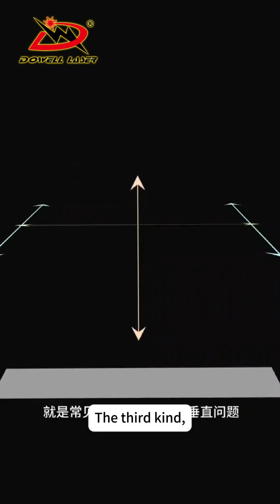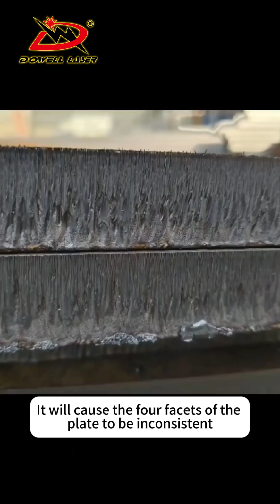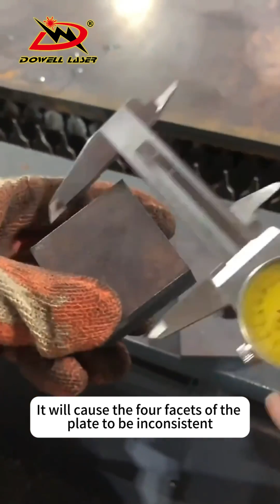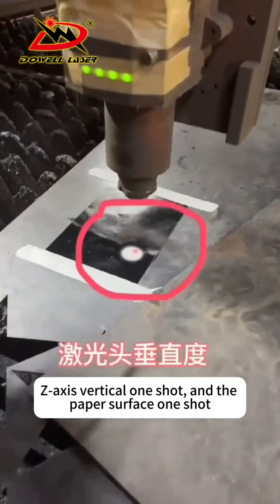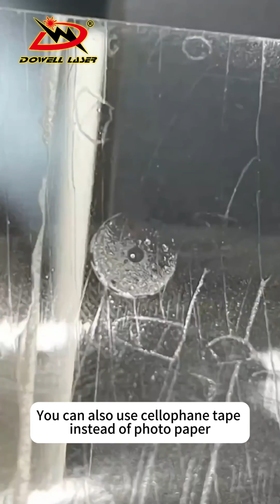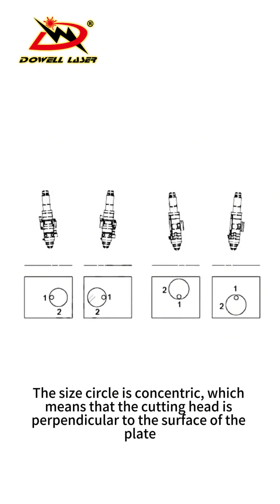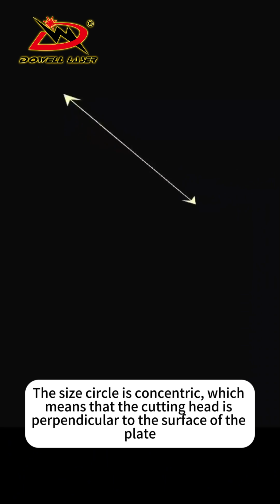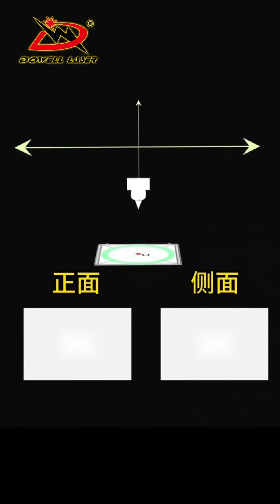The third kind, a common problem, is that the cutting head is not installed vertically. It will cause the 4 facets of the plate to be inconsistent. You can use iron plates and photo paper: with the Z-axis vertical, fire one shot, and the paper surface one shot. You can also use cellophane tape instead of photo paper. If the size circles are concentric, it means that the cutting head is perpendicular to the surface of the plate; if not, it is not vertical. You need to watch the video to adjust.